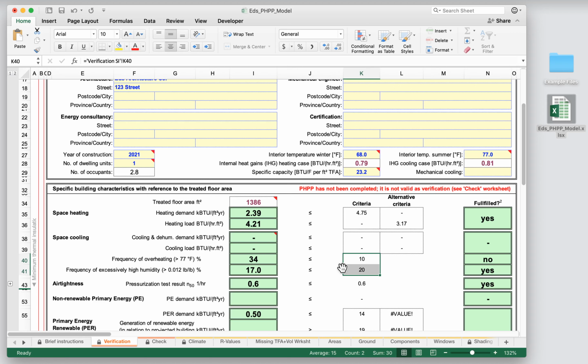Well, as we talked about, there's really two strategies you want to undertake with passive cooling. First of all, you want to try and reduce the amount of heat gain, and then you want to increase the amount of heat loss. So you want to reduce the amount of gain, the amount of sun and the amount of energy coming in, and then you want to use ventilation primarily to take heat out of the building. So let's start with the first one. Let's see what we can do to reduce the amount of heat gain.